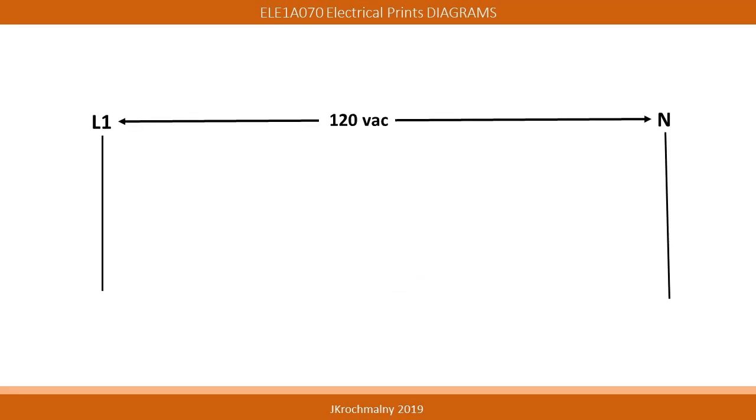We can start our ladder diagram creation by drawing the source of the power at the top, complete with power descriptions. In this case, 120 volts AC appearing across L1 and neutral. Next, we can place into the drawing the 2 loads, the electric motor and the green lamp. Remember, these loads are placed 1 load per rung and located toward the right.